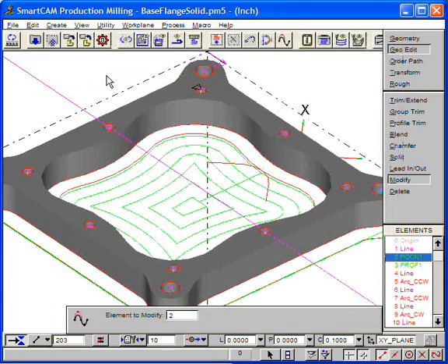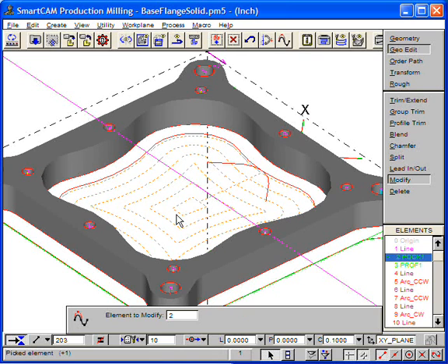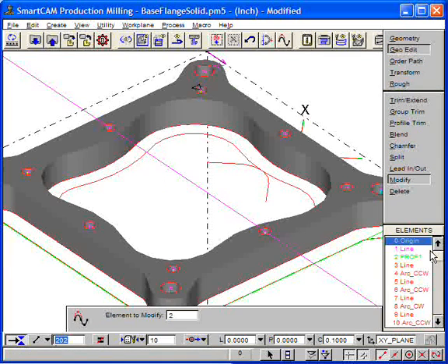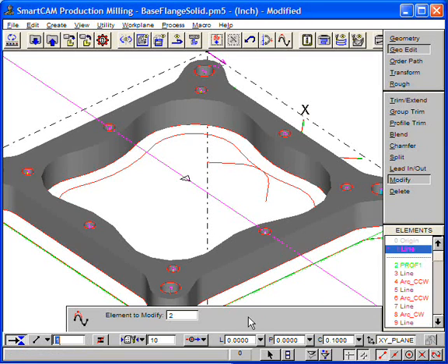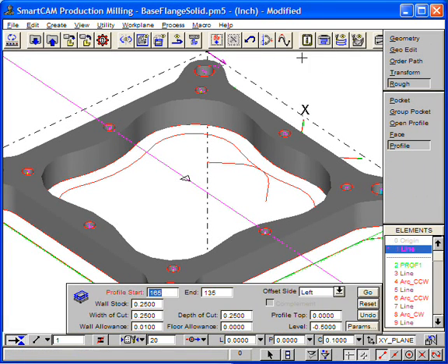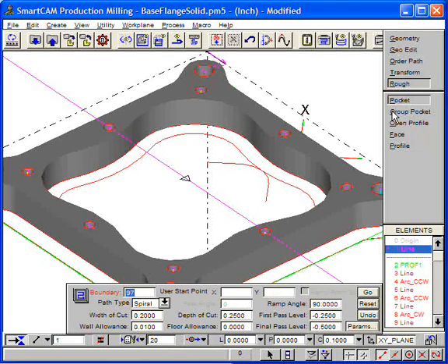To demonstrate the creation of a process container, we will first delete our Pocket Container element and recreate it as a process container. We now set the Insert position and select the roughing step. We select the Pocket Process panel and we turn on the Insert bar, Insert in Container option.